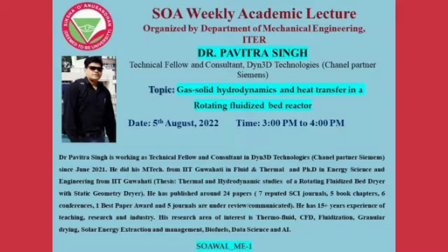So actually air is entering this vortex reactor in the transverse direction, and in the blue color you can see this is the blade slit, and it is separately shown in this figure. This blade slit is diverting the air in the tangential direction. First we have to create the vortex in this reactor by injecting higher velocity air. After confirming the vortex in this reactor, we need to inject the solid particles, and these particles follow the gas path partly and form a rotating solid bed.